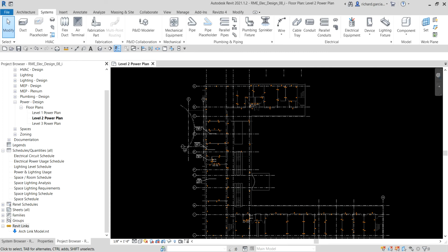In this video, after we learn how to create power loads or power circuits, this time around in this exercise, we're going to begin by balancing the loads at the level 2 and level 1 panels, and then examine the loads presented at the panels to set our final breaker sizes. Finally, we're going to verify and adjust wire sizes that Revit MEP recommends for handling the loads for the circuits. So our topic is about balancing wire size and breaker service. Okay, all right, so let's get started.